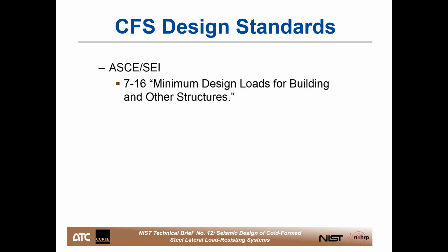And of course, no list of structural design standards can be complete without talking about ASCE 7. ASCE 7, of course, includes provisions for a variety of building materials and systems, where engineers look to ASCE 7 for seismic requirements such as the response modification factor R, the overstrength factor omega naught, deflection amplification factor Cd, as well as specific detailing requirements for a variety of structural systems.